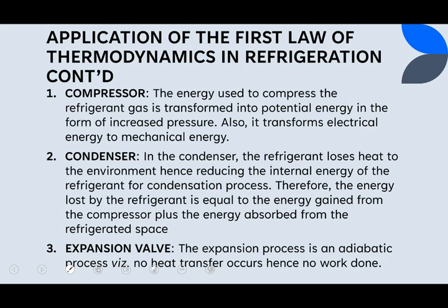Compressor. The energy used to compress the refrigerant gas is transformed into potential energy in the form of increased pressure. Also, it transforms electrical energy to mechanical energy. In the condenser, the refrigerant loses heat to the environment, hence reducing the internal energy of the refrigerant for condensation process. Therefore, the energy lost by the refrigerant is equal to the energy gained from the compressor plus the energy absorbed from the refrigerated space.